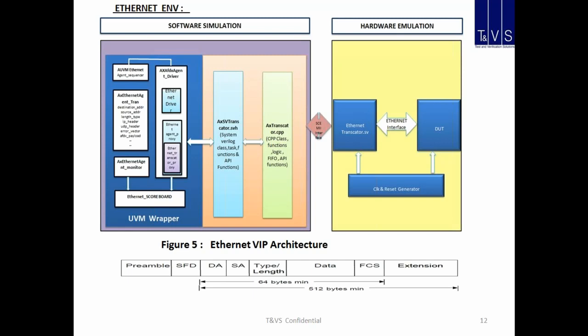Synchronization. Whenever you talk of synchronization, the DPI-based mechanism is not advised, because I have really experienced that I'm missing data, I'm behind whatever is running in the emulator. So whenever you have to synchronize, the DPI mechanism is just to stimulate things.